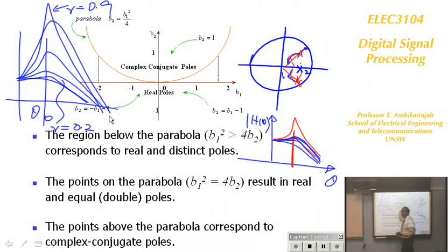That's the resonant curve. The next chapter tells you about the oscillator. What does that mean? That means I am going to move these poles there. They're going to be on the unit circle. They are resonant poles, on the unit circle. If you have it here, on the real axis, there's not much use to it. It's still stable, but it's of no use. But here, if you have a resonance on the unit circle, then it becomes an oscillator. That's the next chapter.